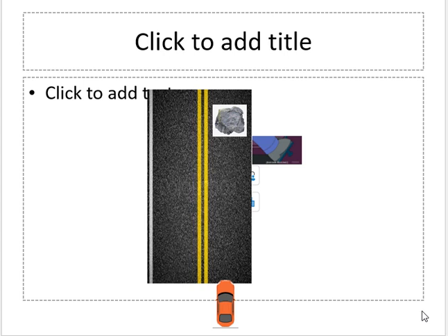Braking time only includes what is after the braking starts. Braking distance only includes what happens after the braking. Perception reaction time is before the braking. You think before braking, right? Your perception reaction is your brain. So this is happening before the braking. After you push the brake, perception reaction is done. Then we have the braking distance only.